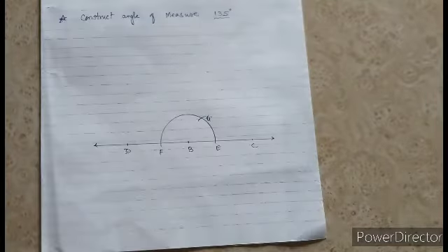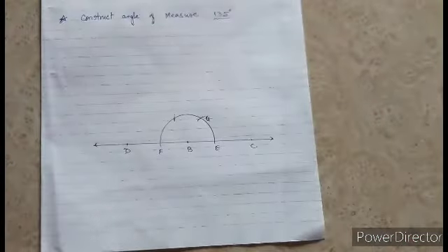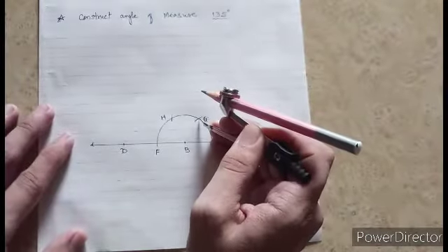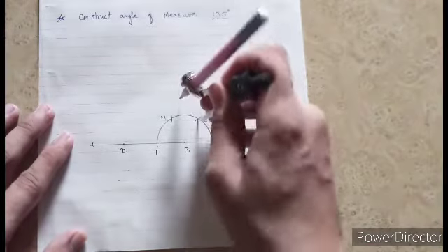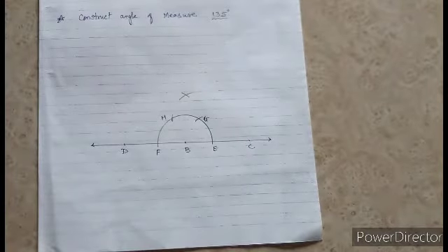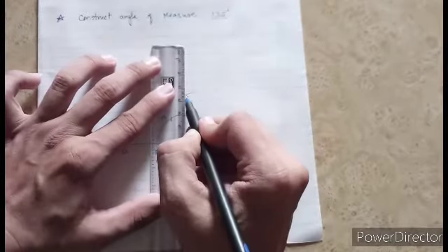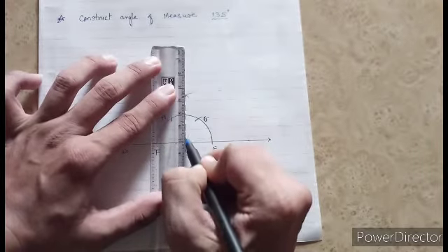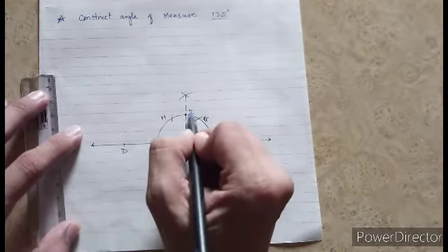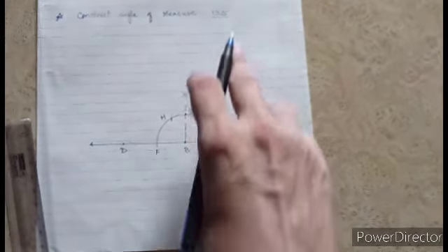G. Now from G point, make another arc on the semicircle. That point is H. And from G and H, we will make arcs one by one. The intersection of these two arcs will give us the reference line for the 90 degree angle. We will draw the reference line for the 90 degree angle like this, and we will obtain a 90 degree reference point I, suppose. So this angle IBC is 90 degrees, but we want to construct a 135 degree angle.